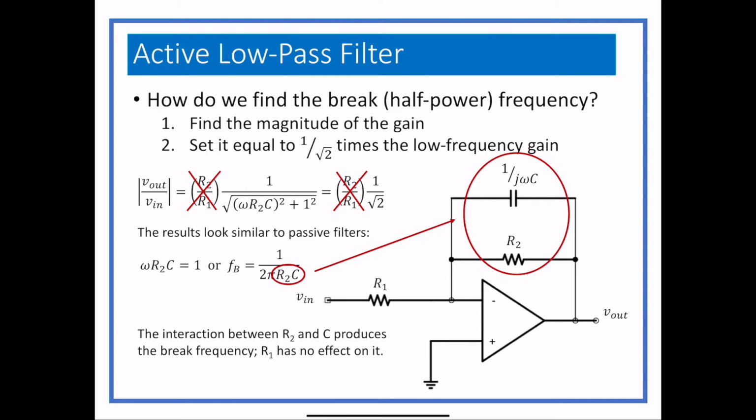So you always use the resistor that is in the closest proximity to the capacitor. You can actually make a kind of a low-pass filter without R2 in there at all, with just the capacitor and the R1, but that's unstable and doesn't work very well. So the resistor R2 is added in order to make sure that the gain at low frequencies doesn't go up towards infinity, because it becomes more and more of an open circuit.